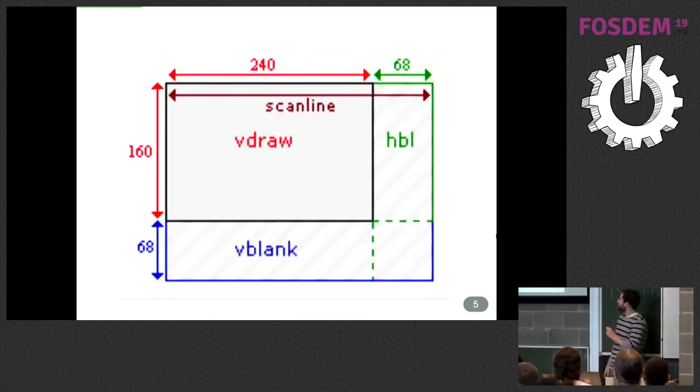Then we have the video hardware, similar to the Atari talk that we saw this morning. You have a scan line that goes left to right and top to bottom. You will have some time between each line, the horizontal blank, and between the end line and the top line, the vertical blank. The interesting thing is that the video memory is actually unusable when the hardware is drawing.